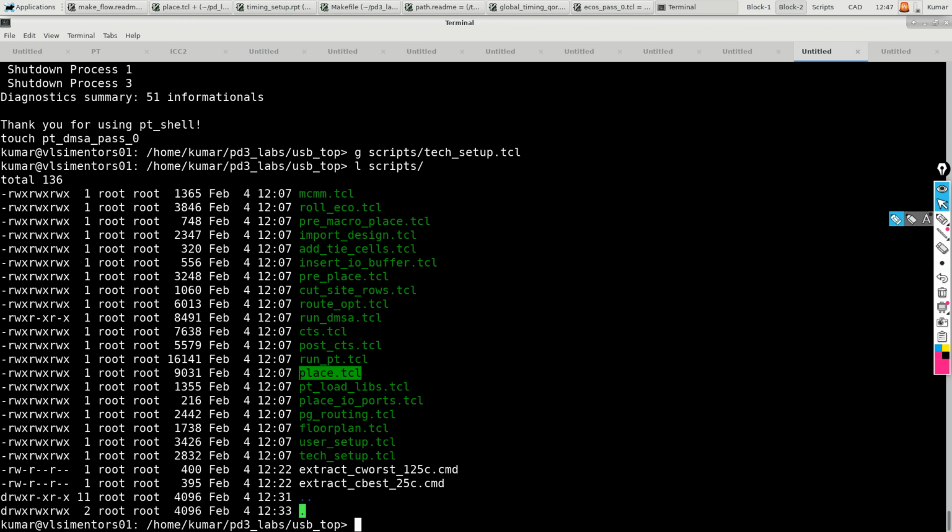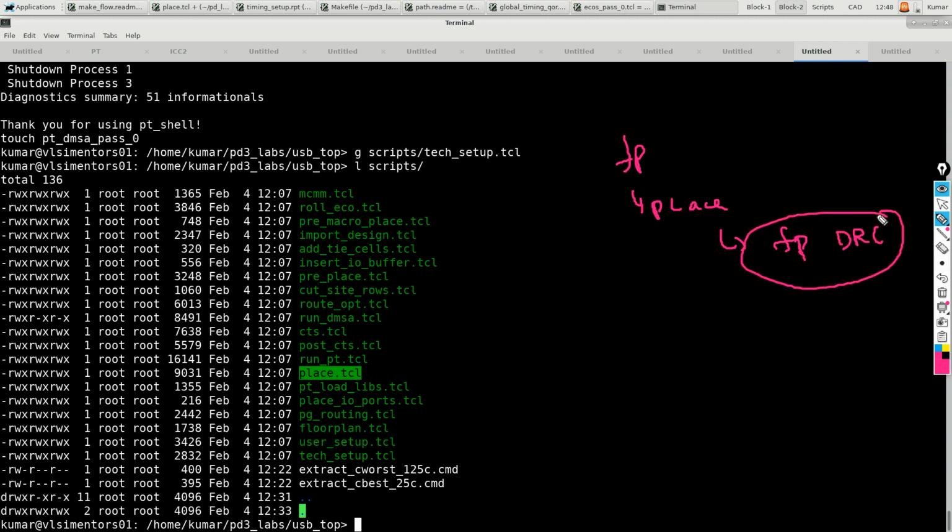Okay, Sri Lakshmi is asking, base DRC, we'll come to know all n-well spacing, all this after placement only, right? No. See, you will actually do a floor plan DRC. So in the lower nodes, for floor plan DRC checks, you do a complete floor plan, then run placement with low effort, or different companies follow different flows. Then run FPDRC where you run only base layers and you can ensure. So in the lower nodes, there is something called floor plan DRC which you need to run.